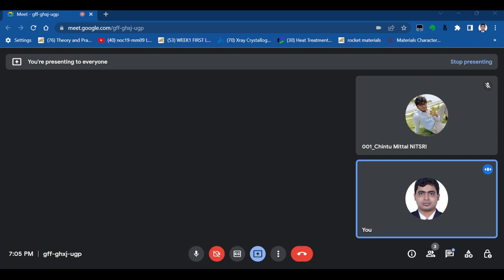Similarly, this is our sigma yy value, and we mark the point for sigma yy and tau xy. We draw a straight line between them, then take half this length as the radius and draw the whole circle. So this is a Mohr circle. Wherever this circle cuts the x-axis, that is our principal stress, this one here and this one here.